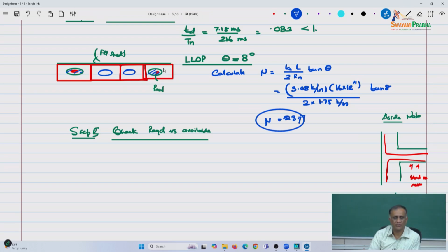So that way the whole unit acts as one. Now the FRP is also going to provide you additional capacities, but not an axial capacity, so that's taken out. The stiffness it provides is very minimal. So it could provide additional capacity in flexure strength due to the FRP sheets.